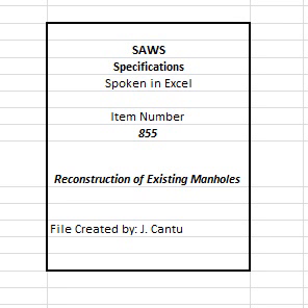5. The manhole ring and cover shall be of ductile iron or gray cast iron construction. The cover shall be solid with no vent or pick holes, hinged with underlying special hinge area leakage protection, the cover secured with 4 stainless steel bolts, and shall have a recessed pick bar for cover opening. Cam lock type covers shall not be allowed.